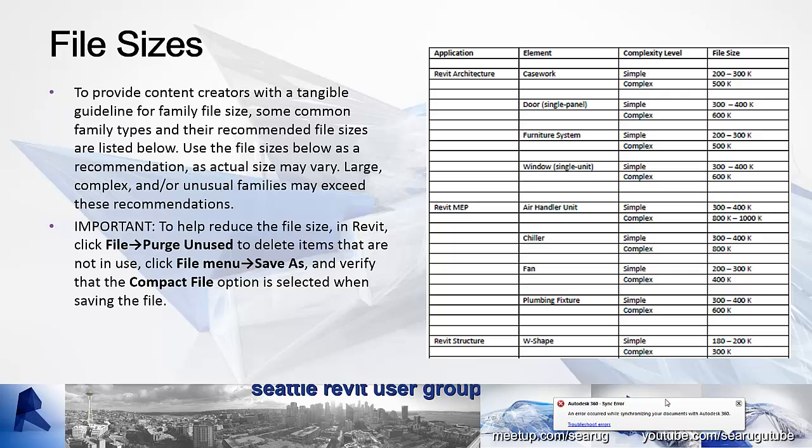Is it AutoCAD data that's just been brought in? Is it exported out from SolidWorks, Inventor, numerous programs out there and just brought in? That's a red flag for me. A lot of the times I can keep my content in the 600 to 700K realm. Now, depending on how many variations you have out there, it might grow. A very complex piece of content, a window, transom, side light, left, right variation with multiple mutton patterns and multiple mutton profiles, definitely could become 1.2, 1.3 meg. But that's acceptable as long as it's clean. It's a simple piece of content.